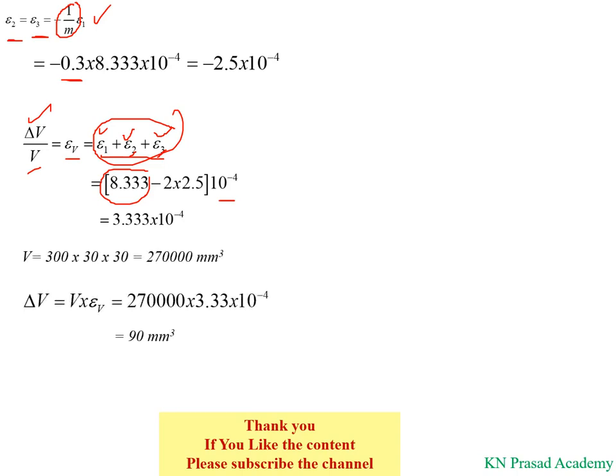Then we have to determine the change in volume. We know the volumetric strain is 3.33 into 10 to the power minus 4, which is the change in volume divided by the volume. So the change in volume will become the volumetric strain into the original volume. Here the original volume is the length into width and thickness, so 300 into 30 into 30.